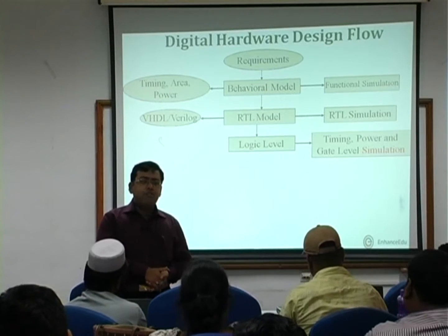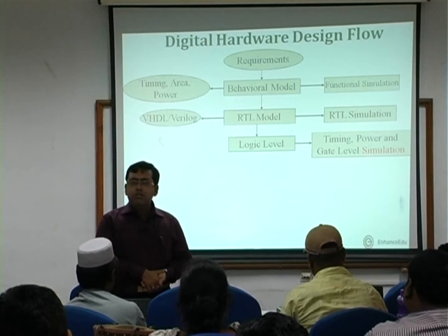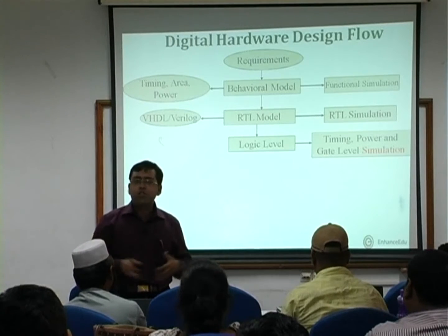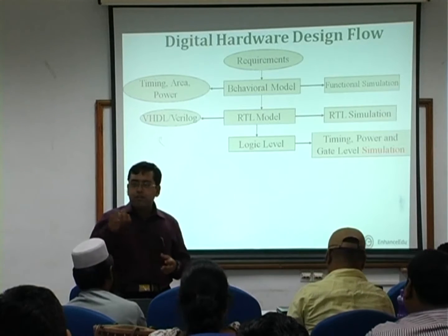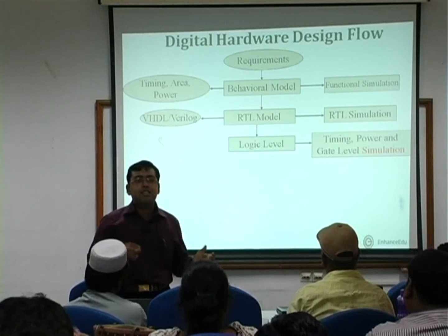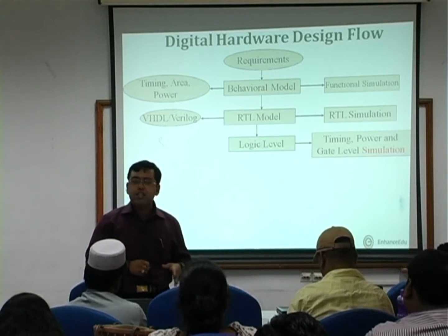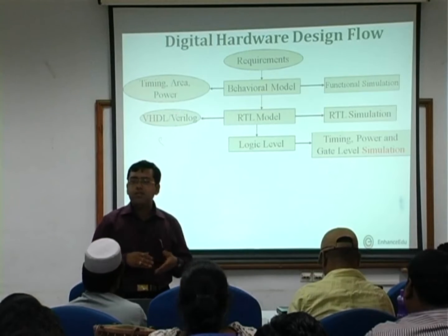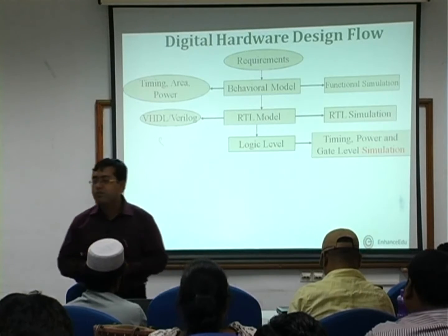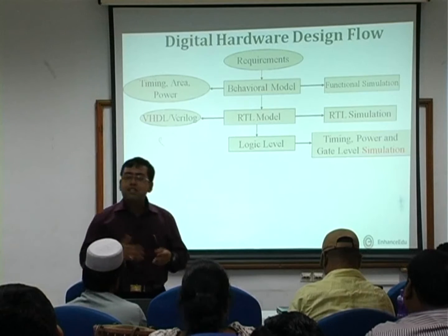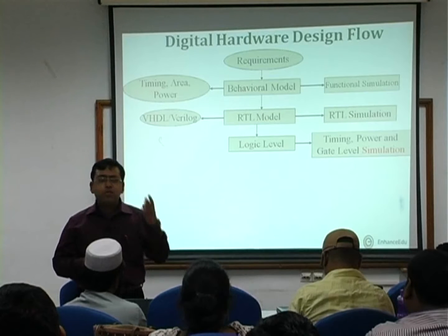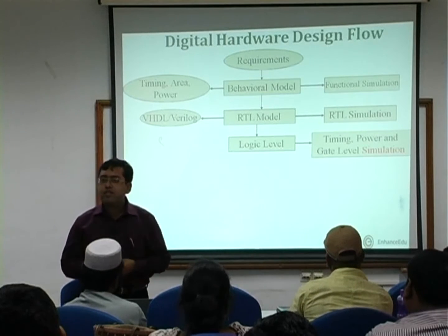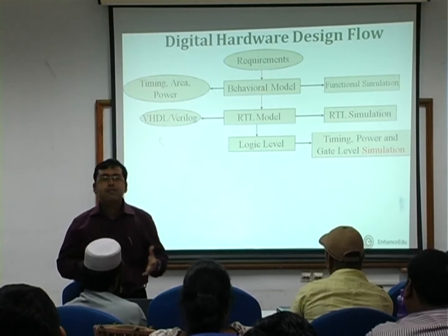No, actually at the logic level we can have an option of choosing what type of logic family we are going to use for further coming down to the transistor level. So once you can define a circuit as an interconnection of logic gates, you can straightforwardly say whether you can go for complementary CMOS logic, or pass transistor logic, or pseudo NMOS logic, or complementary pass transistor logic, or precharge evaluate logic, or domino logic, whatever it be, to implement your circuit as an interconnection of transistors. And depending upon the type of interconnection in terms of the transistor level implementation, you can get an estimate of the power dissipation when you are doing the gate level modeling and simulation.